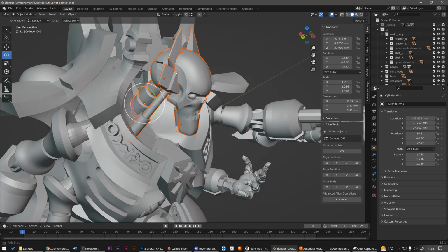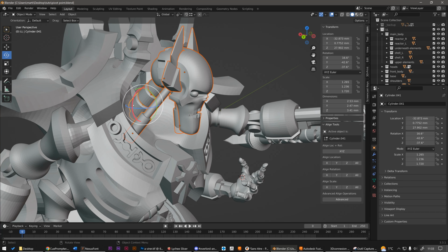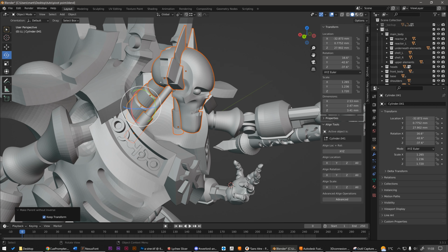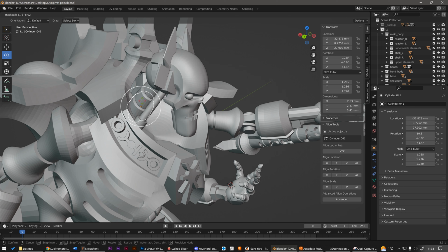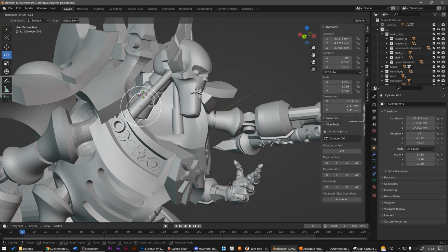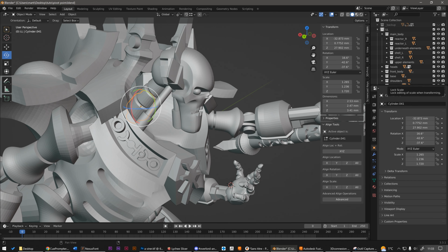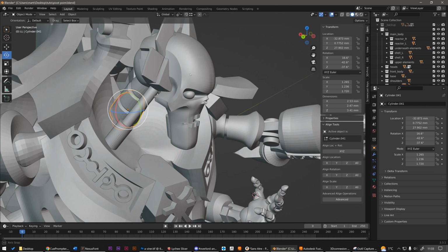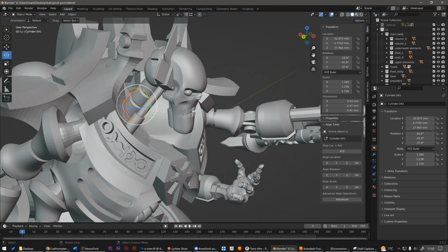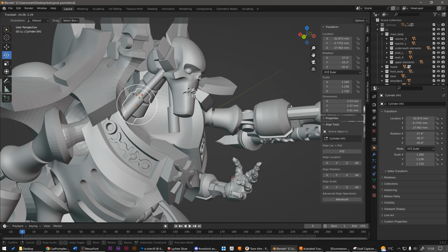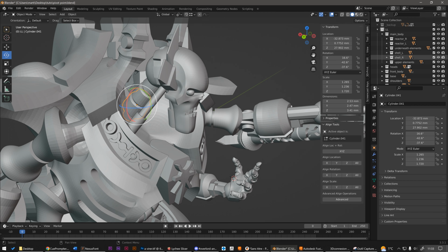We could also have parented all the objects as children of the vertebra. That way, we would just have to rotate the vertebra, and all the children objects would follow. But it depends on the situation. If, for example, these objects are not intended to be linked together, rather than creating a relationship link, doing our rotation, and undoing the relationship link afterwards, it's faster to set the pivot point like we did.